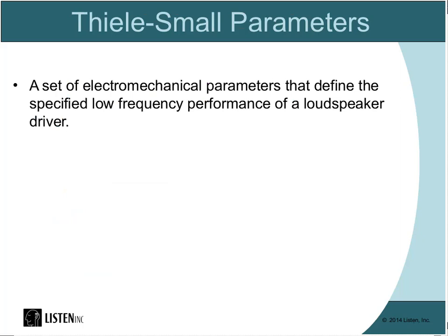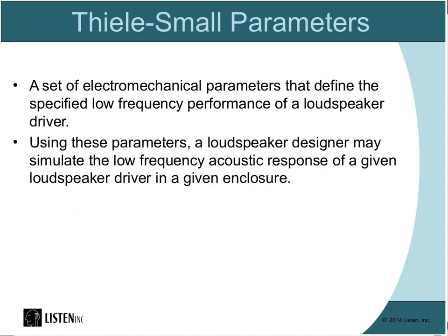So, speaking of Thiele-Small parameters. Thiele-Small parameters are a set of electromechanical parameters that define the specified low-frequency performance of a loudspeaker driver. Using these parameters, a loudspeaker designer may simulate the low-frequency acoustic response of a given loudspeaker driver in a given enclosure. So basically, we can measure the impedance of a loudspeaker in a couple of different ways, and from that, we can actually model the low-frequency performance.